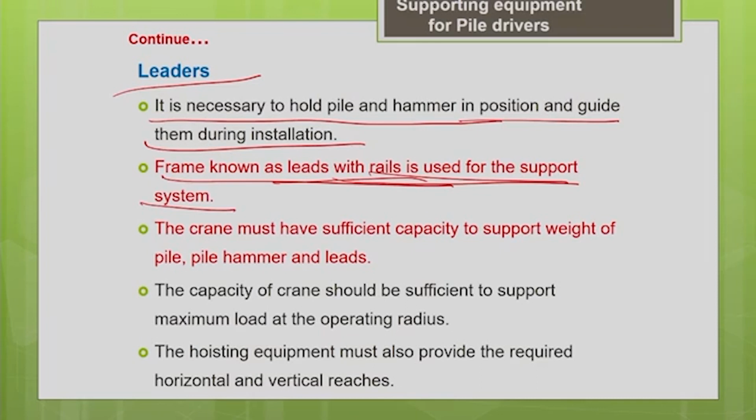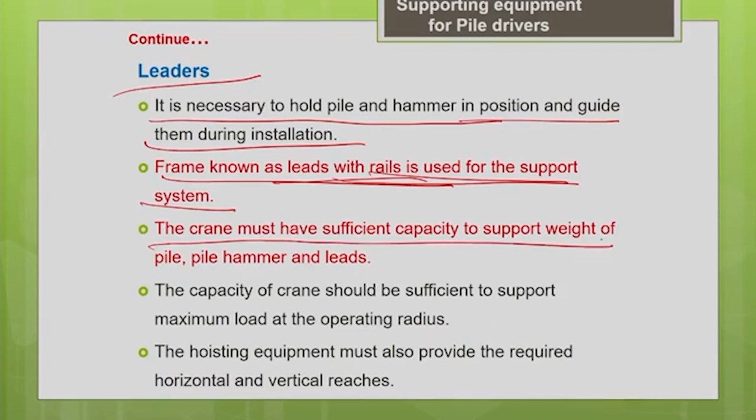And one more important thing you need to know: whatever lifting mechanism you are going to use, maybe a crane, you have to check the lifting capacity of the crane, whether the crane has sufficient lifting capacity to lift your pile, hammer, and to hold your lead, everything in position. The crane must have sufficient capacity to support the weight of the pile, hammer and the leads.